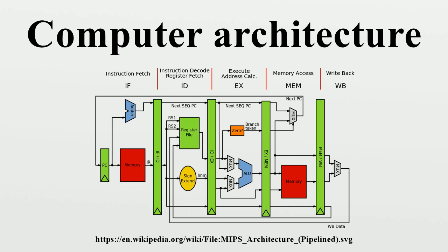Also, messages that the processor should emit so that external caches can be invalidated. Pin architecture functions are more flexible than ISA functions because external hardware can adapt to new encodings, or change from a pin to a message. The term architecture fits because the functions must be provided for compatible systems, even if the detailed method changes.